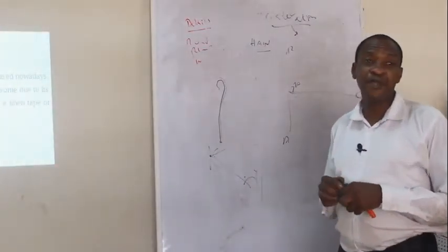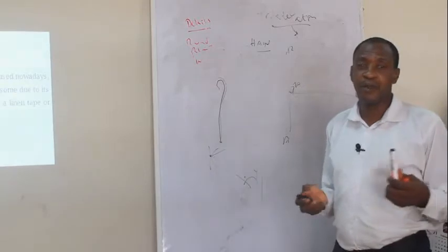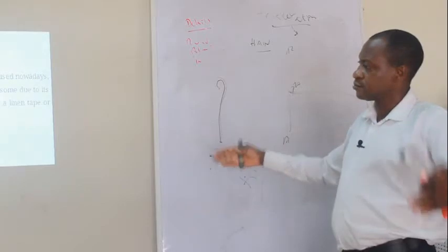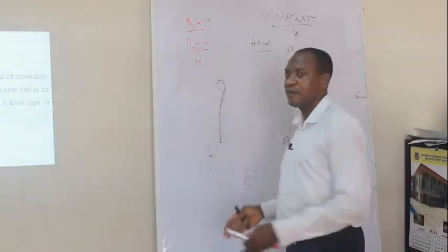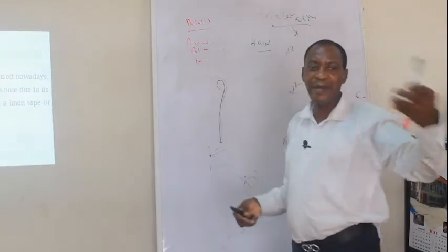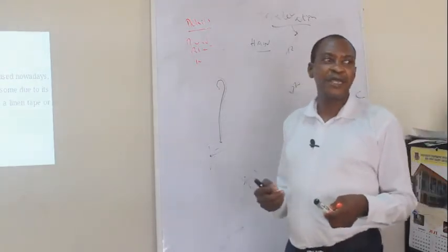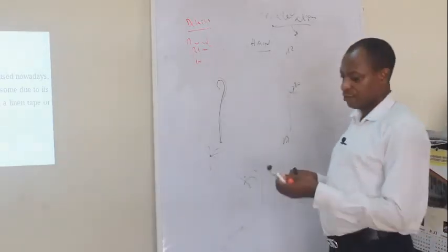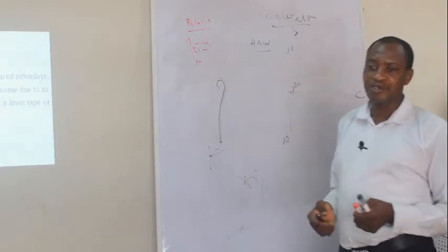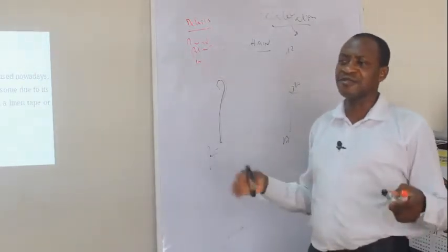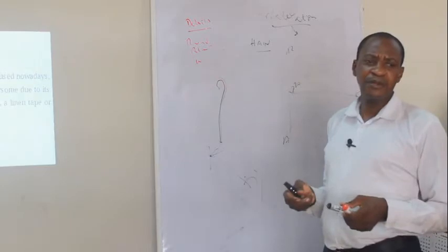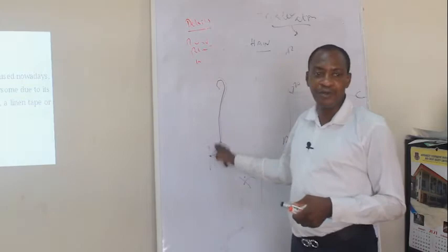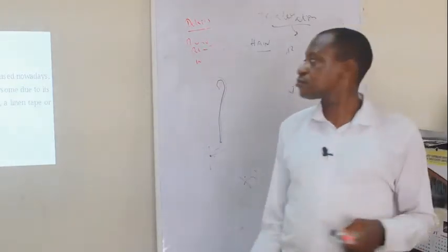Assuming you want to measure 500 meters now, and you have a 100-meter tape. If you stretch the whole tape on the ground, and you move to another one again, by putting arrows there, somebody at the back coming, picking the number of arrows, can tell you how many times you have measured 100 meters. But if you don't have that arrow, somebody can say, oh, I measured that line 4 times. Somebody says, no, it was 5 times you measured. Or somebody can even say it was 3 times, because you are not consistent. But the arrow can tell you to dispel that kind of doubt.